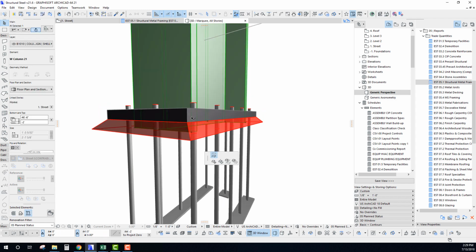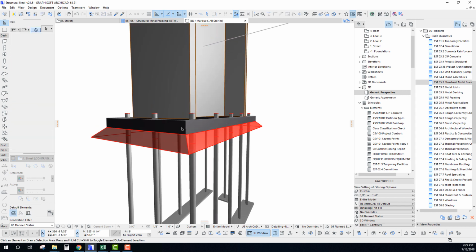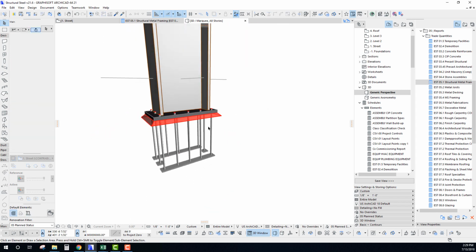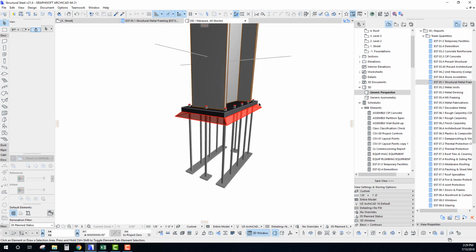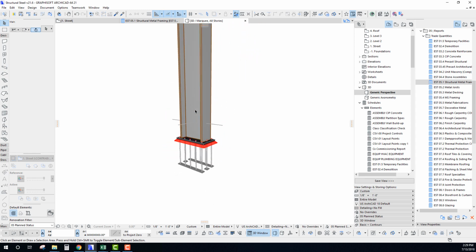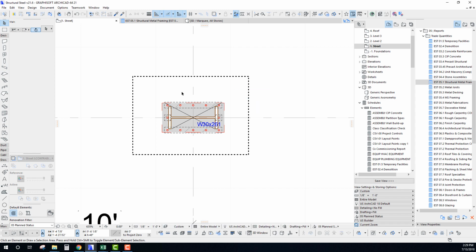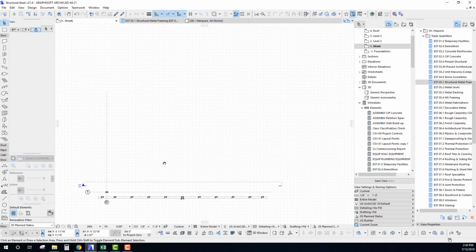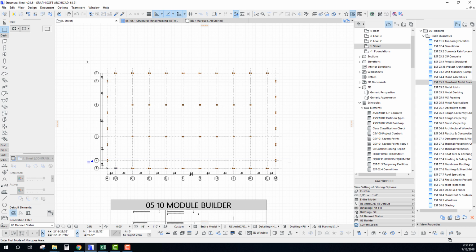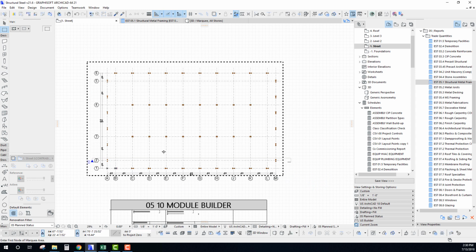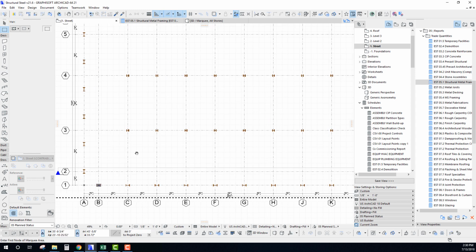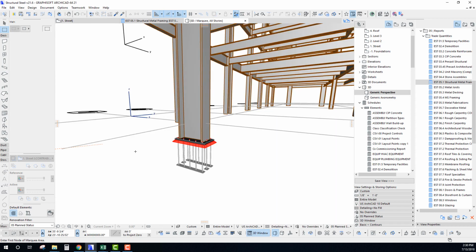And then from there, we can, of course, adjust our column height. So now we've gone down to 46.2, so we're dialing in that height a little bit. And now we're also adding base plates for all of our different columns here. So, okay, with that, because I'm going to copy this around, I'm going to adjust all those column heights.